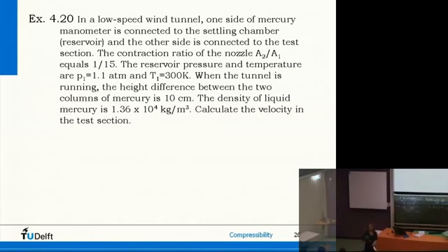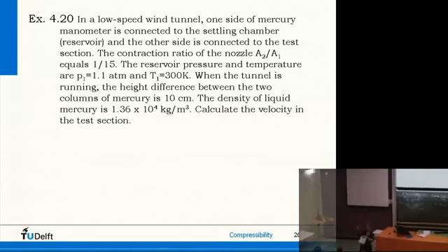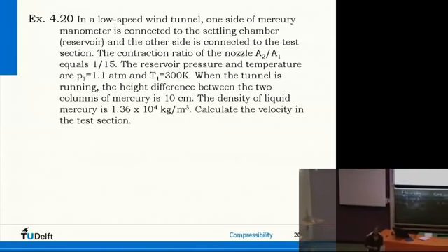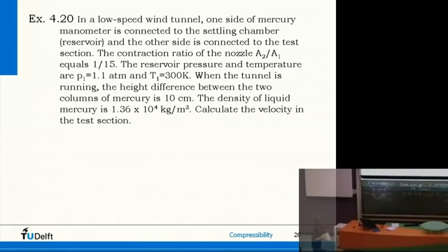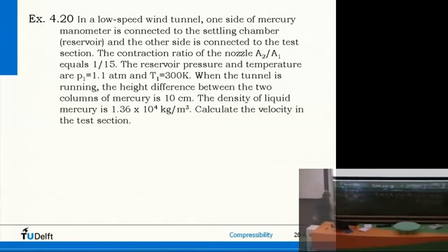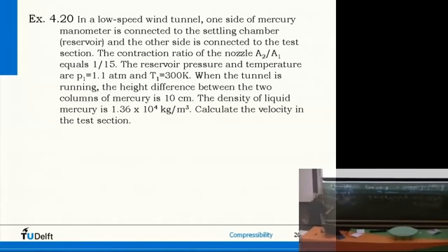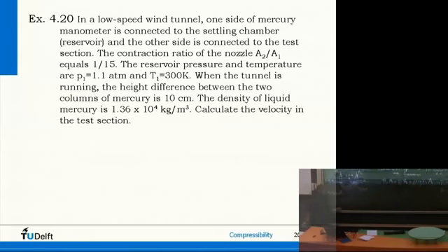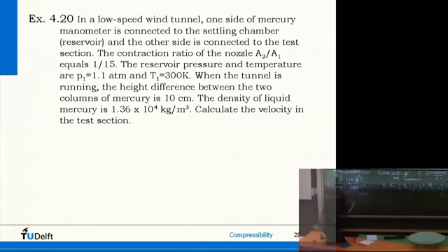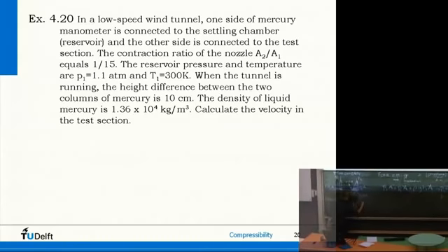So it is true, low speed is given. I would recommend, once we have calculated the speed in the test section, which is the fastest section in a subsonic wind tunnel, to check that it's not way beyond 100 meters per second. But good point. So Bernoulli relates pressures to velocities. That is, P plus a half rho V squared is constant.